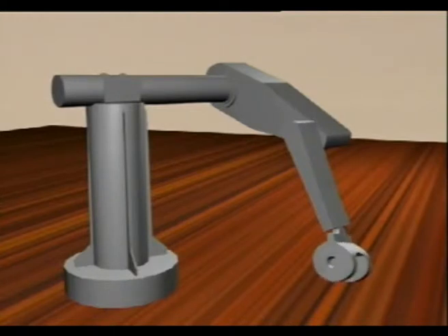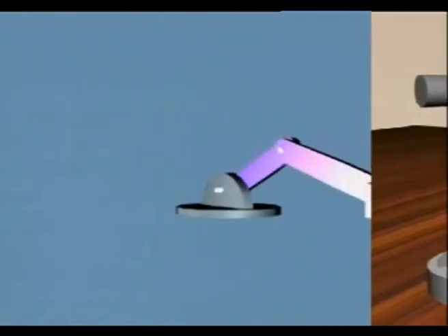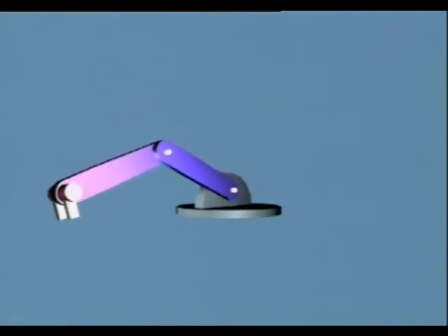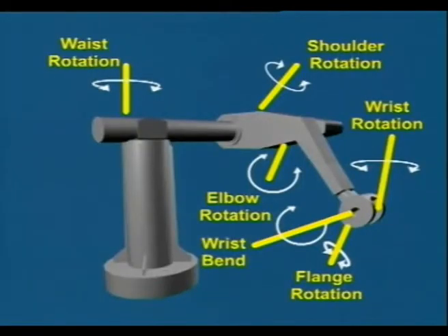And now we are trying to show a robotic arm, which is an articulated robot arm. Why have we chosen an articulated robot arm to introduce this industrial manipulator? Because it is similar to a human arm. It can be modeled as a chain of rigid links interconnected by flexible joints. Links correspond to such features of the human arm: waist, upper arm, forearm, while the joints are shoulder, elbow, and wrist joints. At the end of the wrist, it is connected to an end effector, which is also called a gripper or hand, or sometimes a tool is held in the end effector.